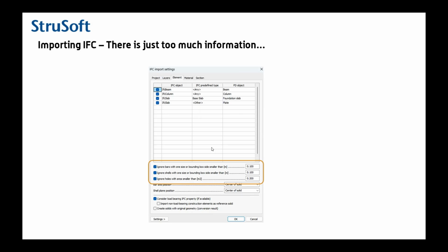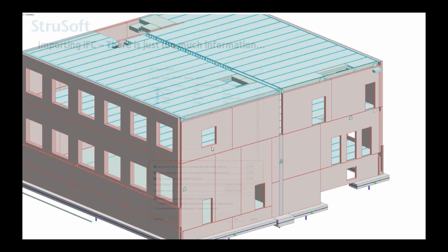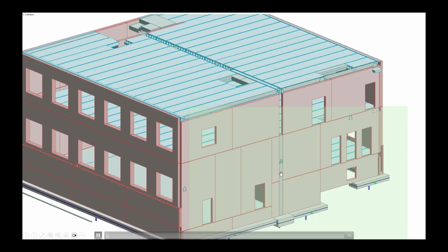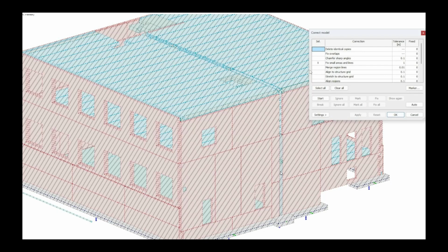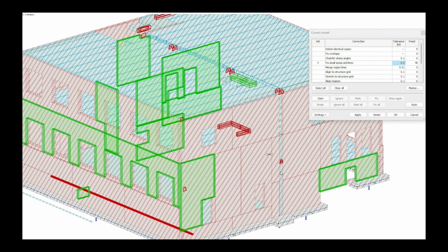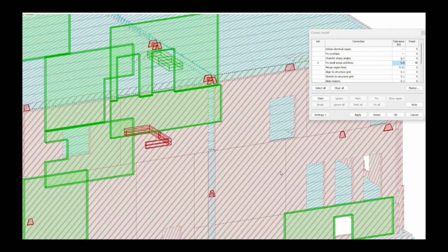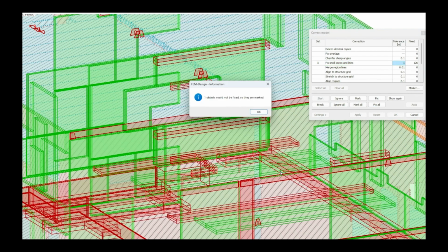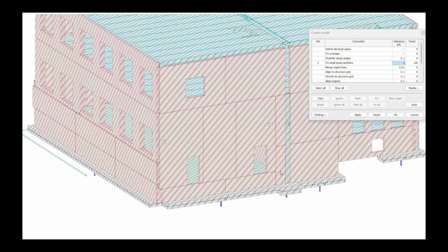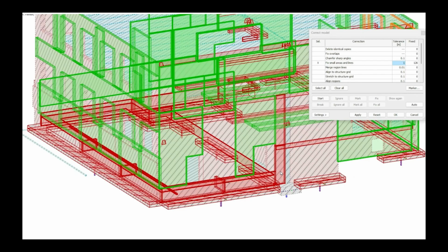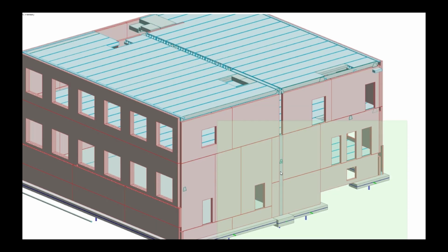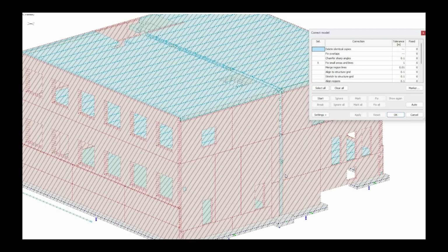And then you can filter by size. Examples of this are probably easier to see here in the animation. If we take a typical IFC and we filter by size, we can set the size to 0.3 meters. And then we can see the unnecessary elements, like the red ones, that will be taken out of the IFC file. There are a lot of steel plates and grout of concrete and things like that. And if we put the size to 1 meter, we can also get rid of the foundations or even small beams and things like that, to get only walls. So the size can also be a classification filter.